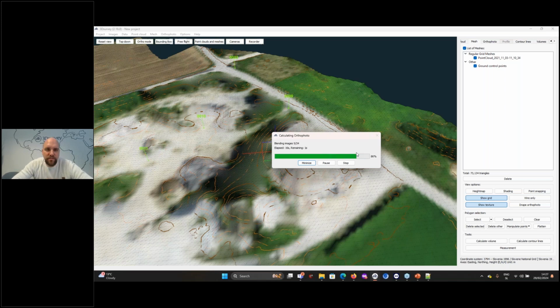First, images are being reprojected onto this digital terrain model and dewarped, changed to orthographic projection. Then in the second step, colors between images are harmonized, so that when we create an ortho mosaic from our aerial photos, it will be hard to tell which part of the orthophoto was calculated from which image.